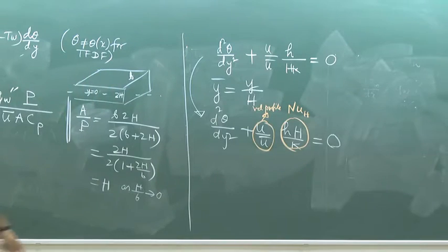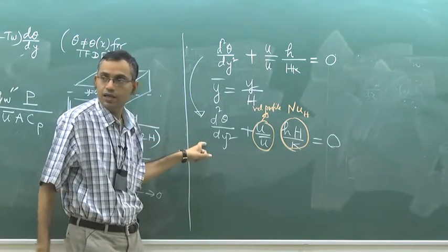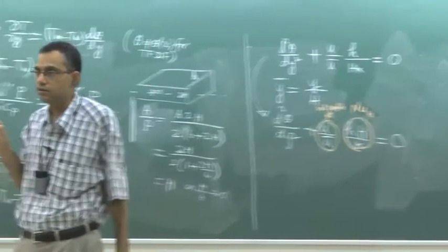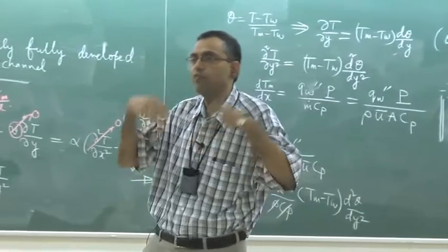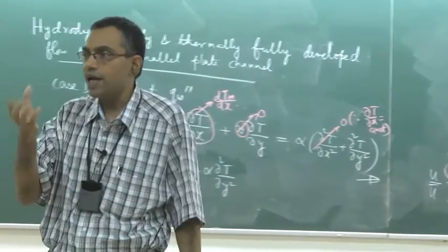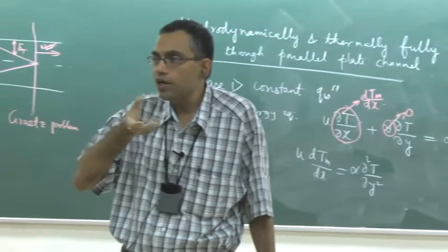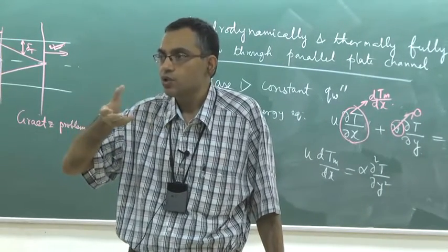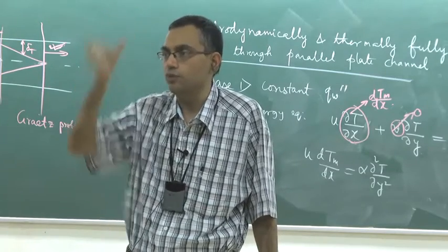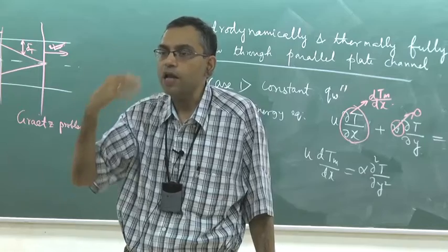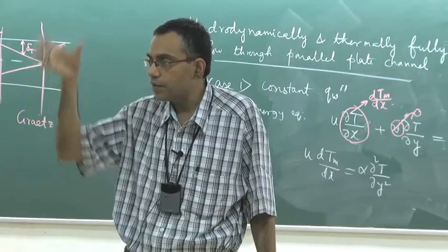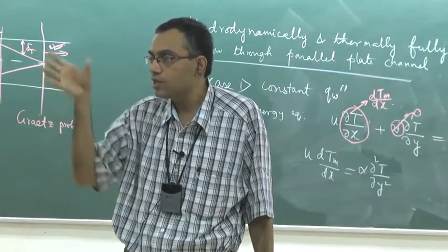So the answer how theta will vary with y will depend on what? It will depend on the velocity profile. Now there are many types of velocity profiles which are possible, like there may be a case when molten metal is flowing very slowly. So in that case the entire velocity profile may be almost uniform, and that is called a plug flow or slug flow. So if you have a plug flow or a slug flow, that means uniform velocity profile, then what is u by u average?